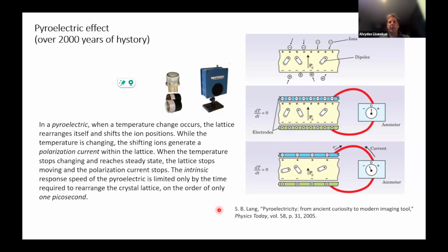So what is important with the pyroelectric phenomenon? It is just a creation of temporary voltage in response to variations of temperature. If the temperature varies, then, for example, polarization changes, and that creates a voltage change, which is compensated in the end in several ways, either by leakage in the material, or by ions from the surrounding space. So actually, it's just a variational effect.